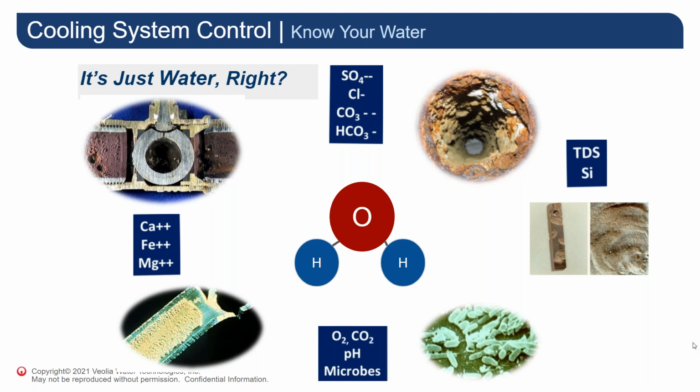High dissolved solids will limit the water's efficiency by influencing how effectively you can cycle up or recirculate the water in your system. And in excessive amounts, silica can also exceed solubility limits and lead to some very insulating deposits, which can threaten system operation and heat transfer efficiency.